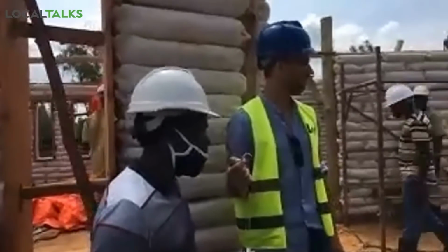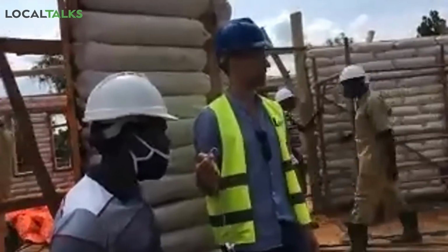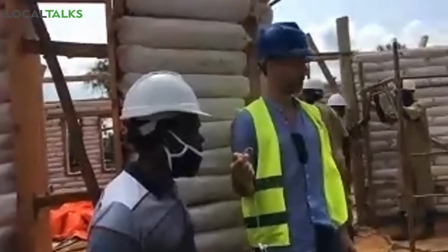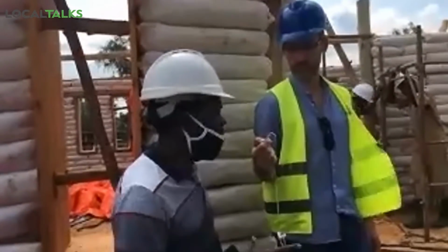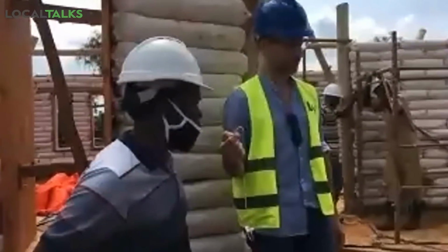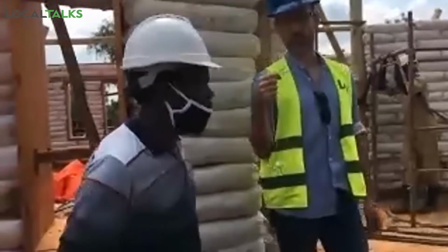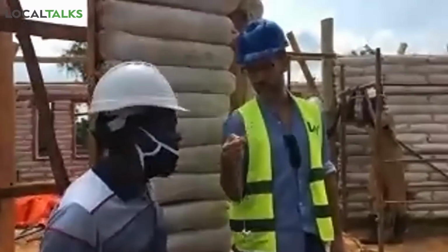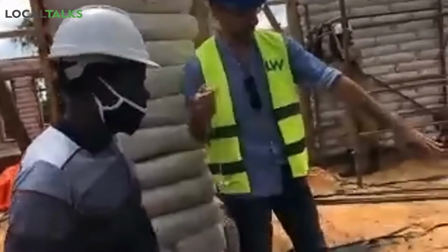Well, this kind of earthbags, the way we designed it, was actually not meant to carry more floors. So we wanted some level of consistency, and this is just a small area of the building. It didn't make sense to reinforce one part, so just for consistency, we decided to build a structural frame. And I think you also said that it would need stabilizing if you wanted to go multi-story, which we didn't want. So this detail shows quite clearly how we've done it.